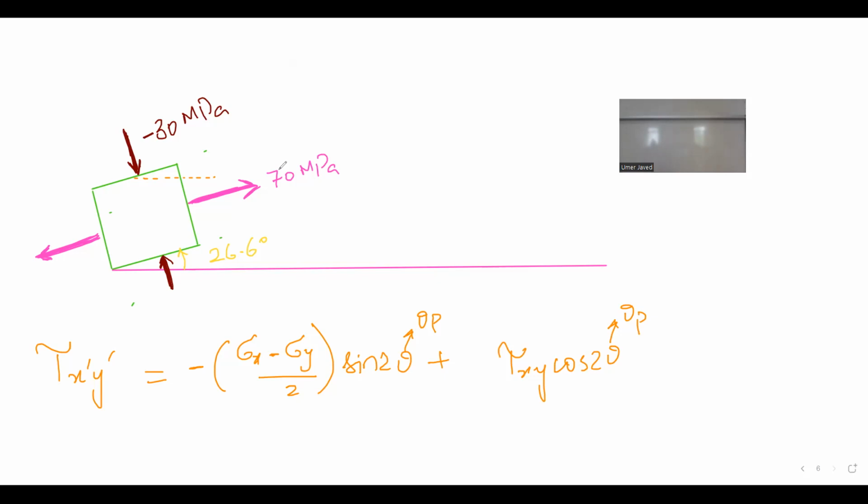This is anti-clockwise, right? So here, is this the x surface? There is no x surface here. There is the x prime surface, so focus on x prime. This is x prime, and the arrow is in this direction, right? So it's clockwise, so this has to be a negative 7.5 megapascal. Tell me whether I got negative 7.5. Yes. Exactly. So I'm saying look at the x prime or x and see the feel of clockwise or anti-clockwise.